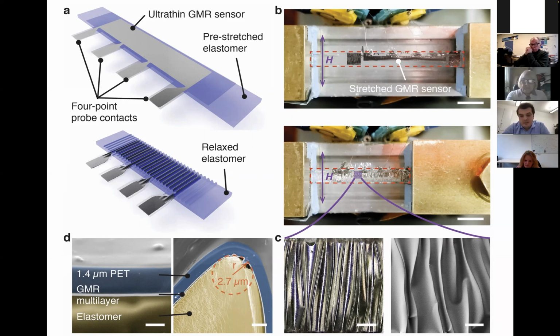What is important here is not the big bending radii, about 3 micron, which is already actually fairly small, but these small wiggles which are around. And these small wiggles, it's a paper from 2015, we still don't know why it doesn't break. So just think about it, you have a 100 nanometer film, which is bent with a curvature radius of, well, obviously sub-micrometer, and it doesn't break, yeah?